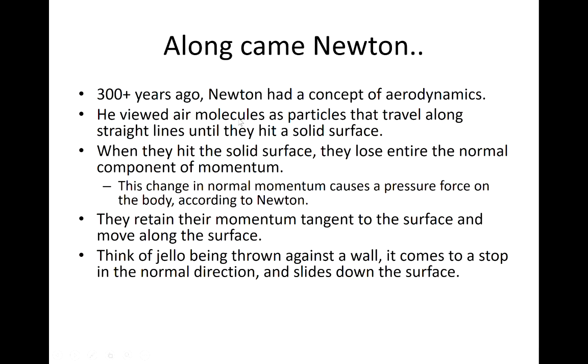So Newton said, I'm going to model fluid dynamics. He didn't know about hypersonic aerodynamics. He thought all fluid dynamics. I'm going to use my Newton's equation of motion of the particles. So he said all the particles travel along a straight line until they hit the solid surface, but they go through an inelastic collision. That means it's like a rubber ball that's got not much air inside. So when it hits the surface, it does not bounce back.